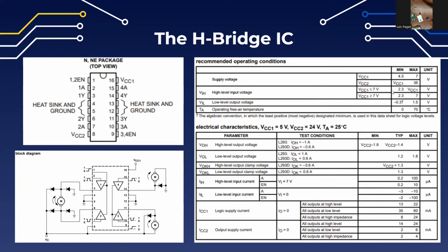There's obviously a lot more information on the actual data sheet itself regarding specific ranges of operation, temperature, whatnot. But the important part is the minimum and maximum voltage inputs that you can use. And for some of the logic on the board itself, the input needs to be of a certain threshold to count as a high or a low. That's defined by the schematic, with the 1.5 and here the 2.3. Anything above that is considered high.